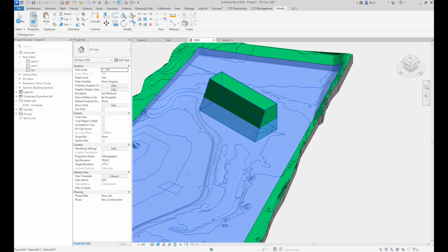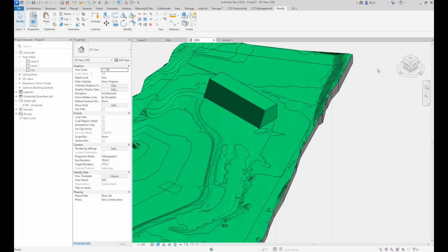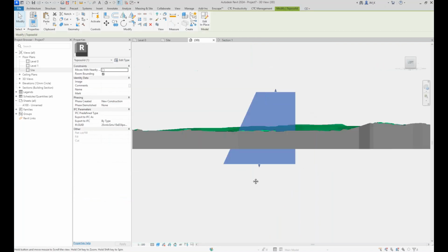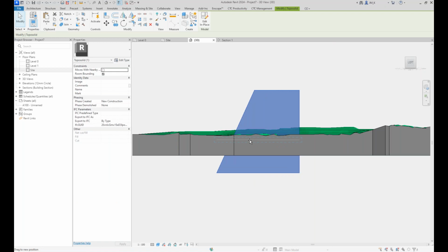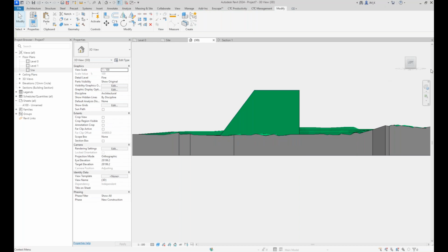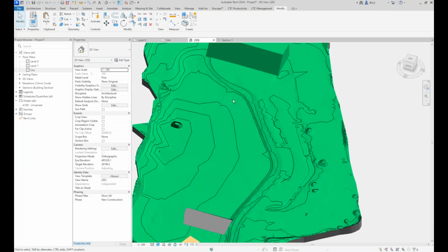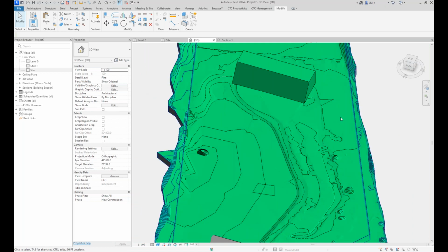Okay. So because I've used join geometry there, Revit will sort of pretend that they are one continuous piece of construction, even though I've done some weird stuff here. With that, okay, so that's another thing that we can do if we needed to represent something with sheer sides on it. You couldn't do that really with Revit toposurfaces, that's for sure.